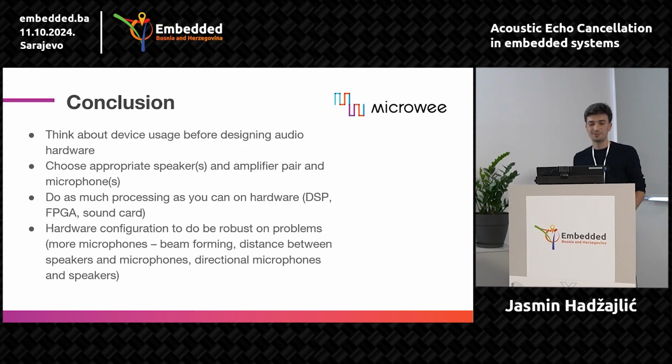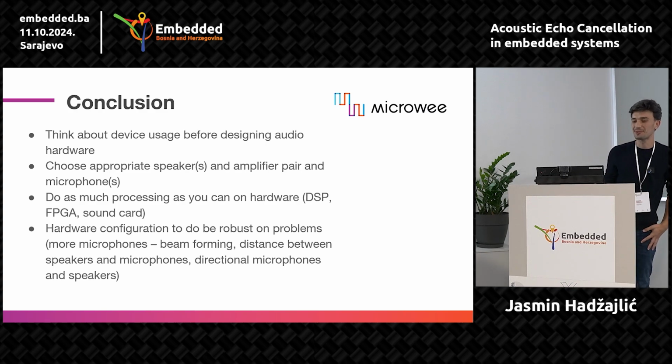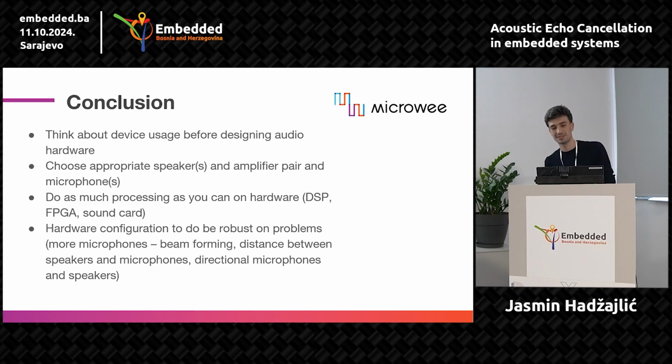And then I can move to some conclusions or advice if anyone wants to take on work on acoustic echo cancellation. Before designing a device, before designing the audio hardware, everyone should think about what it is used for. And as you saw in our case, that was the actual problem. We were using a wrong speaker and amplifier pair. Also, that's the second point.